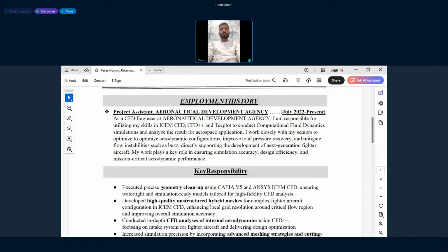So the intake has to be such that if the flow strikes the wing, vortices will come, some swirl will come and affect the intake also. Because of the wing, the flow to the air intake, the angle of attack to the intake, will be reduced. The flow is already turned parallel to the wing, so it is directed towards the air intake. So the angle of attack the air intake faces will be less.